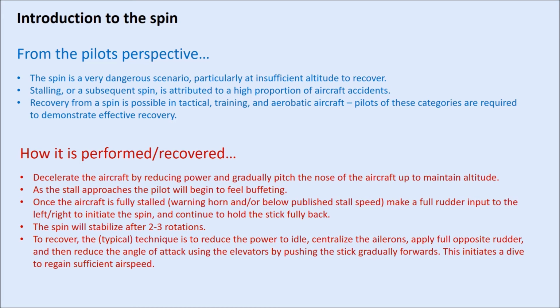The pilot will continue to hold the stick fully back to keep the aircraft fully stalled, and with the rudder pedal in the particular direction that they choose fully pushed in that direction. So that will enter the aircraft into the incipient stage of the spin. The spin will stabilize after a couple of rotations into the developed stage, and then to recover, there are several techniques depending on what pilot manual you read, but the typical and generally accepted technique is to reduce the power to idle